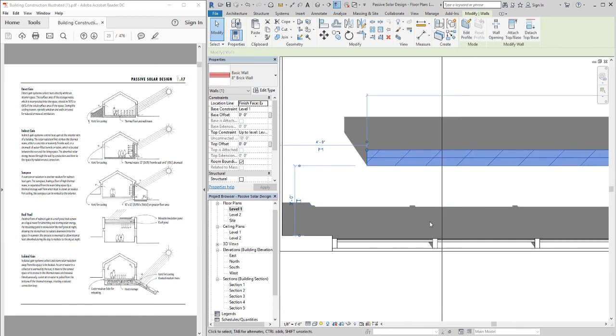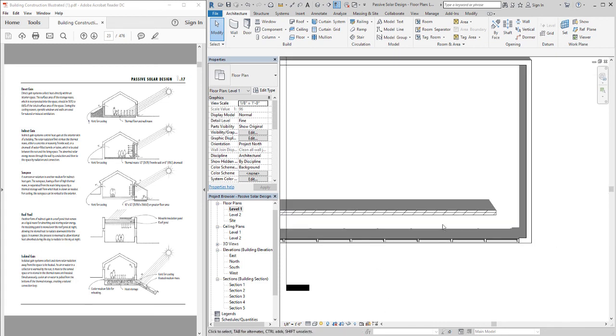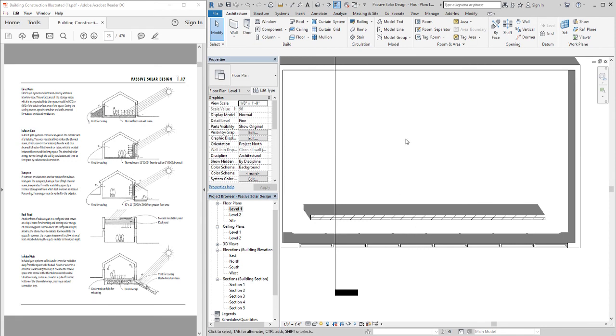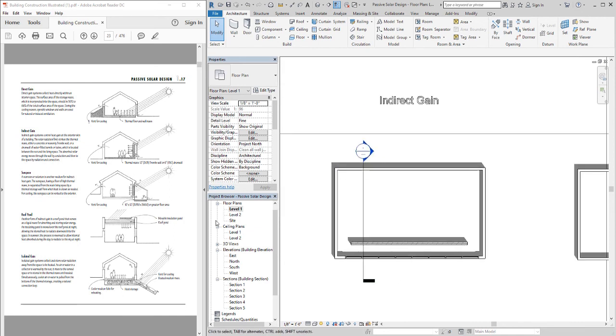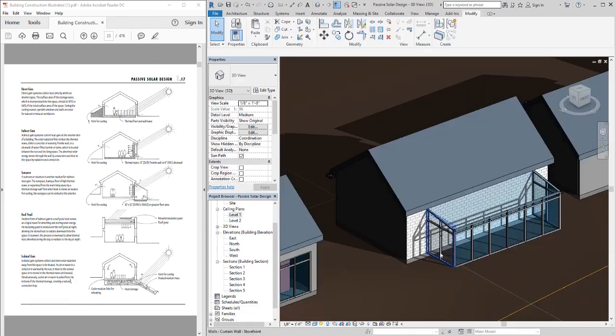We can do this hallway that's on the outside of our structure that then captures all this sun, and now this radiates off into our house after the sun is set. So we have the thermal insulation here, but the heat can pass through with radiation. So that's indirect gain, and our windows then you'll see in the section passing through.